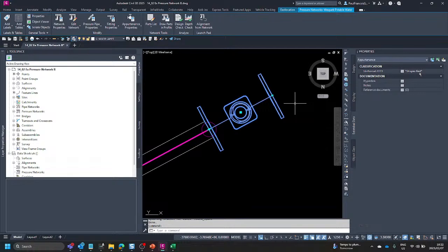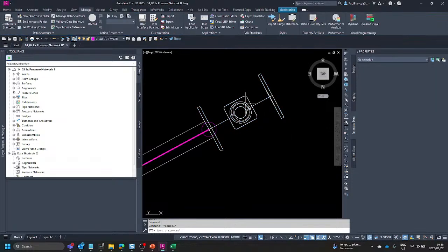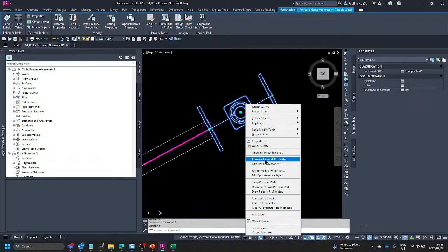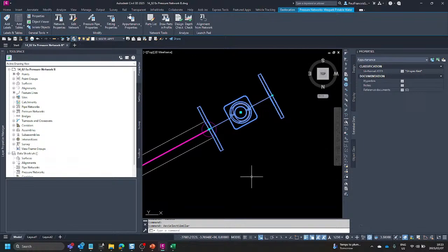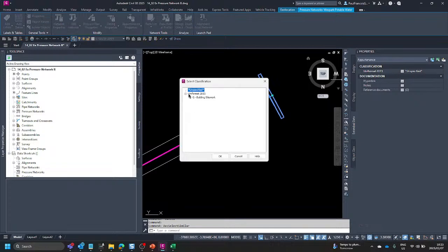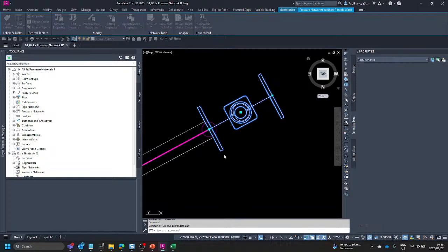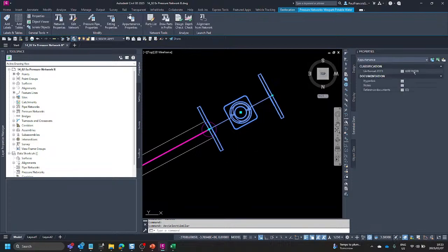And we would like to assign the relevant coding to those elements of that type. A relatively easy way to do that is you would right click and select similar. There's only one of them. And we would then click on the Uniformat 2015 and apply the coding that would say it's potable water distribution and storage. And that then applies the code of G3010 100.